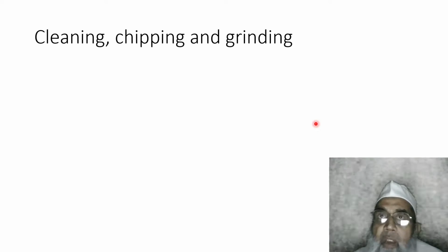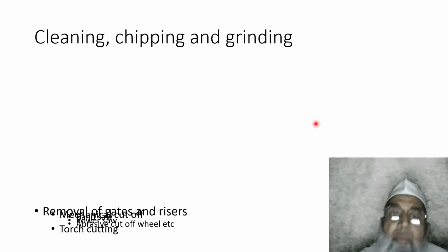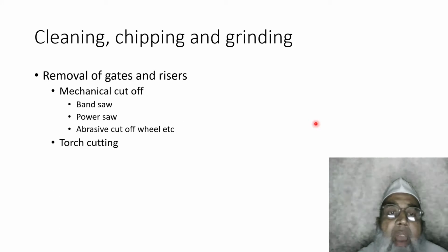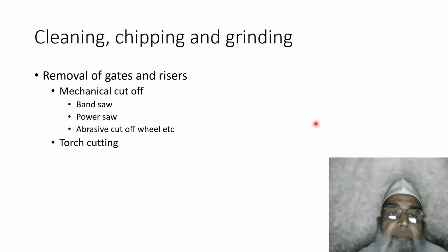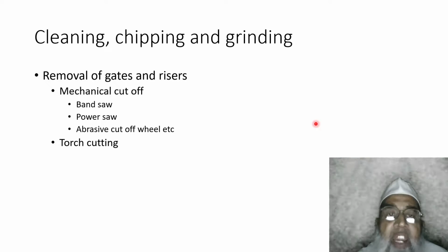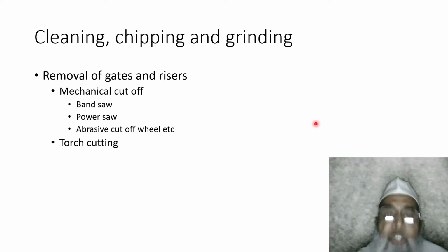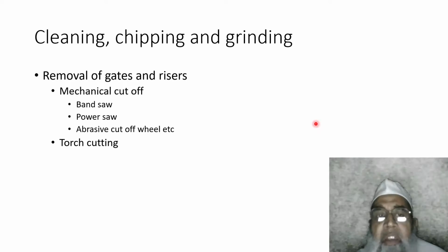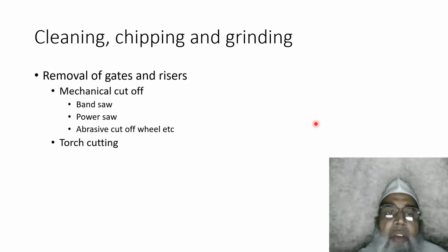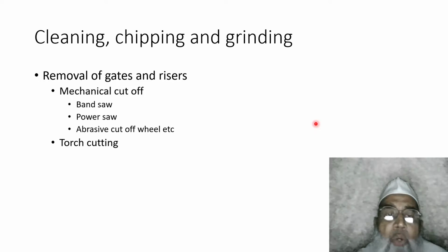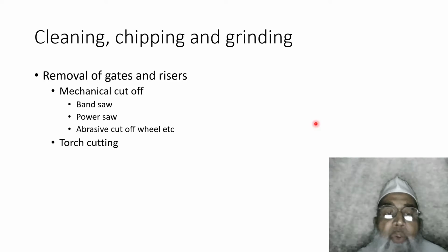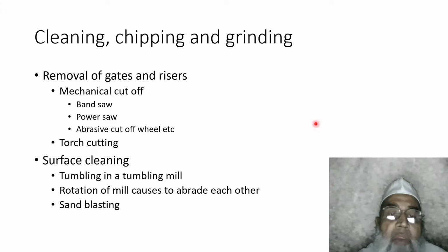Now, after solidification, we have to take out the casting. The removal of gates and risers is to be done by mechanical means like band saw, power saw, abrasive cut-off tools, or a torch cutting mechanism.